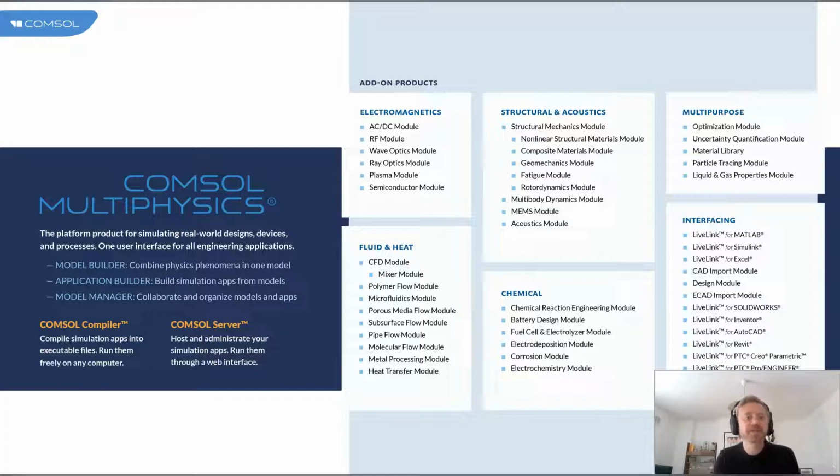Now, this provides flexibility because it allows you to look at branching, for example, and at initiation, but we will sacrifice some accuracy in terms of stress intensity factors at things like crack tips. There is also a crack feature that you can use that will give you an accurate stress intensity factor calculation, but that is mesh-based, so is limited by meshing. So you can't look at propagation using that method.